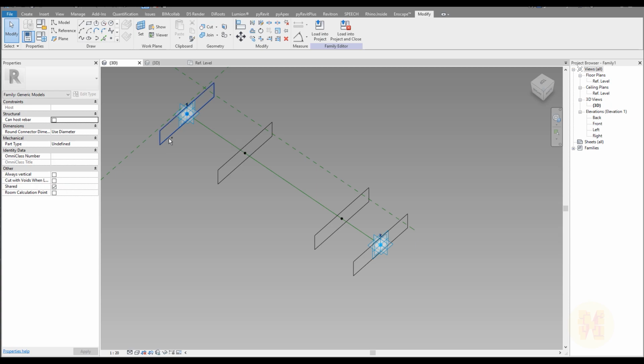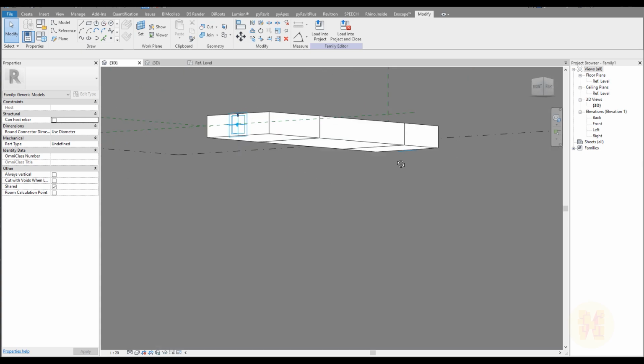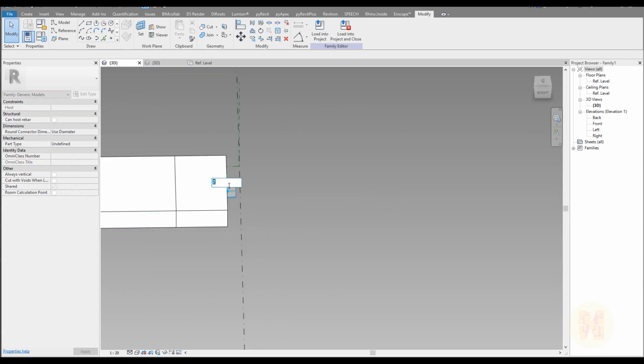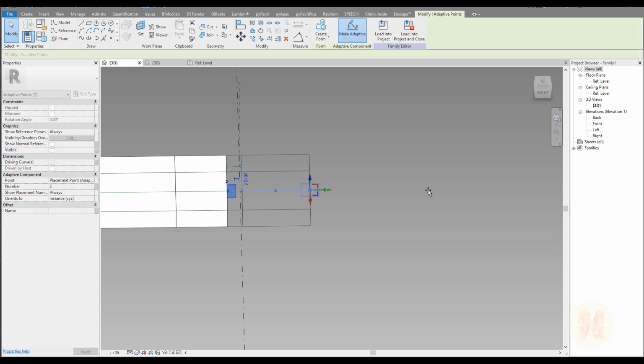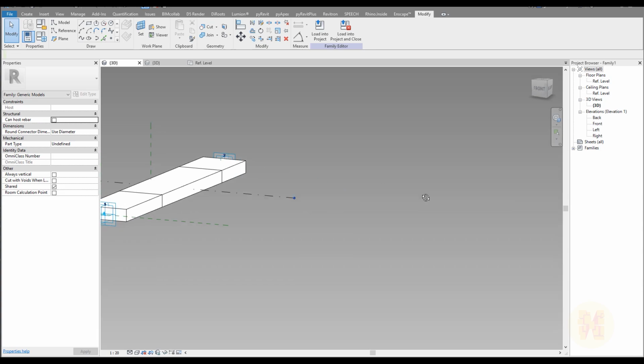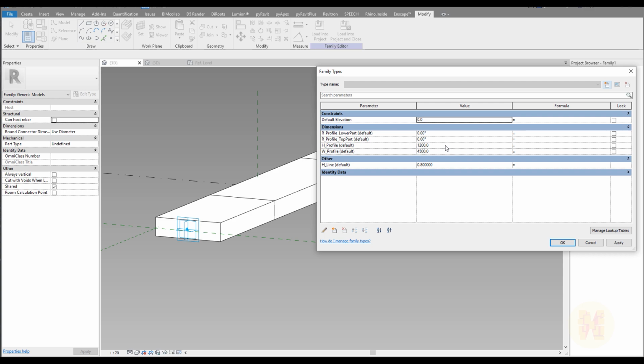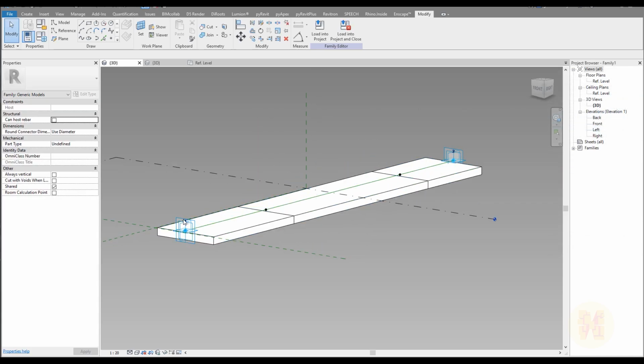Now let's select everything one by one, like we already did. Let's create our form. Here's our form, as you can see right now. I will make the height a bit bigger than we had before, like this. So we did it. Actually, I don't like the thickness, so we have a thickness of 1200 mm. It's too much, I think. Let me make it like 500. Much better, but again we have the same problem.